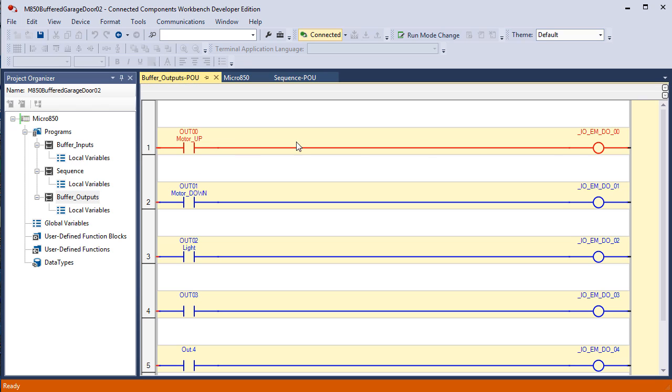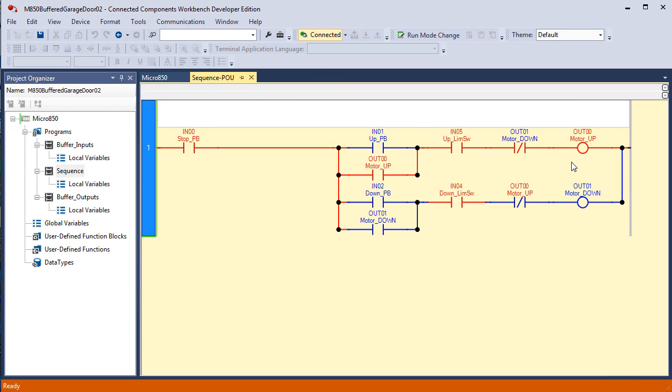See, there's output 00, and it's turning on that module defined bit. However, just because you're feeding most likely 24 volts to the coil on the starter, remember that's a contactor that has big heavy contacts that can switch in a motor that draws a lot of current. Just because you turned on that output doesn't mean that there's continuity from the output of the controller to the coil on the starter. So there's a point where you can have a loss of connection.